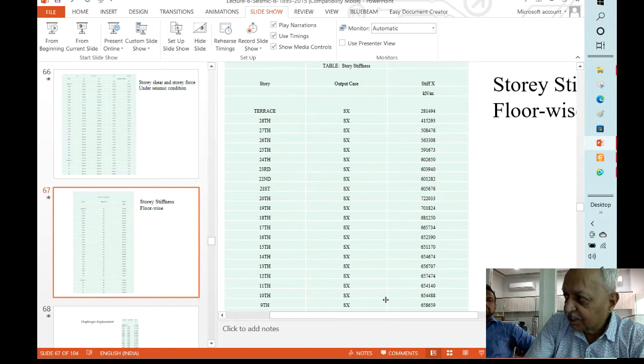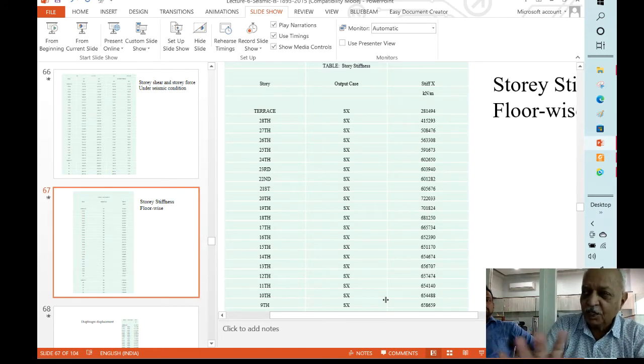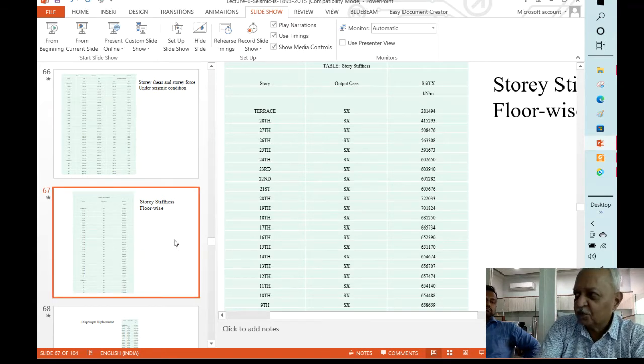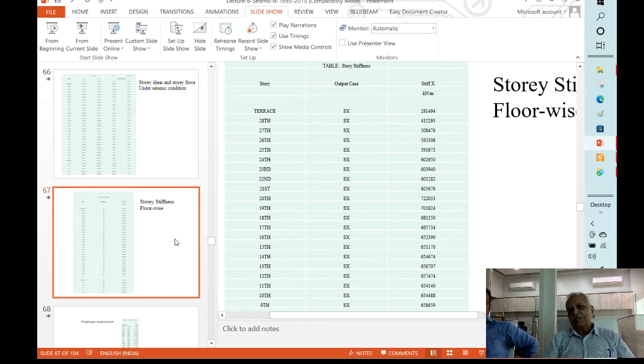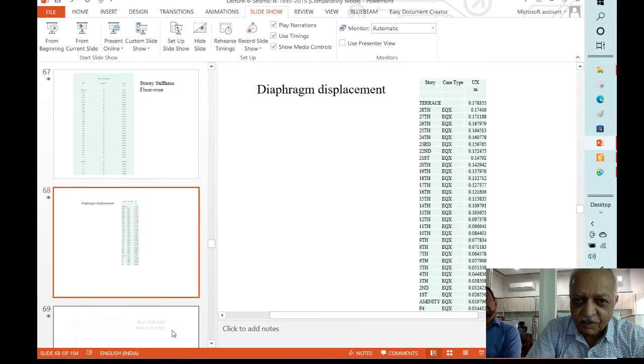Now to understand whether a floor is a soft story or not, you have to calculate the floor stiffness. So fortunately you don't have to do it, ETABS is doing that. ETABS is going to give you ready-made. Only you have to understand, oh, this lower floor has got lesser stiffness than the floor above. So that is very simple. So once you realize, oh, this is a soft story, your design forces are to be considered 2.5 times increased seismic force and the gravity loads as they are, and accordingly you are considering the design of the elements.